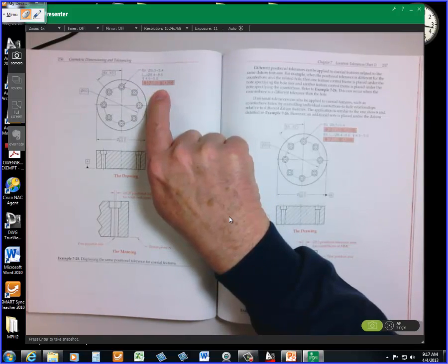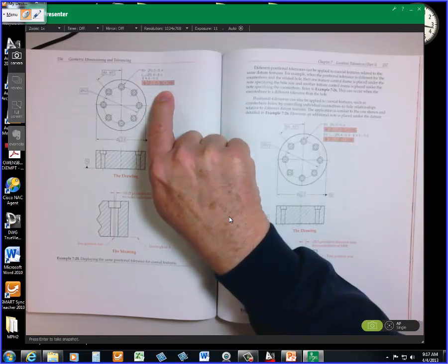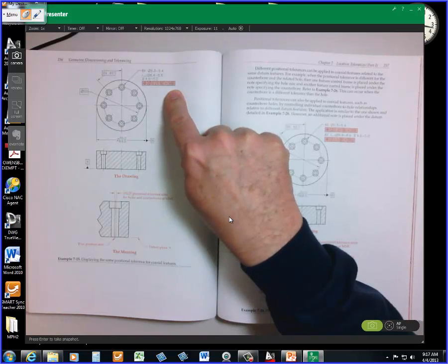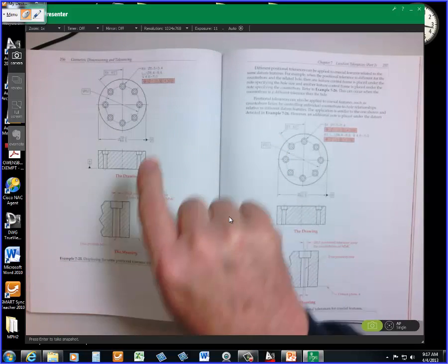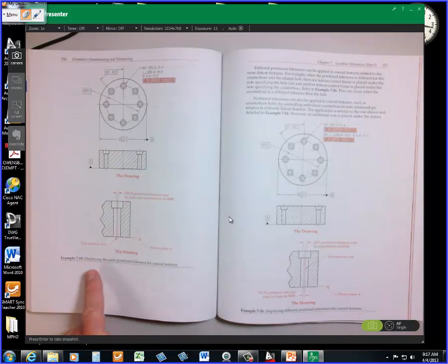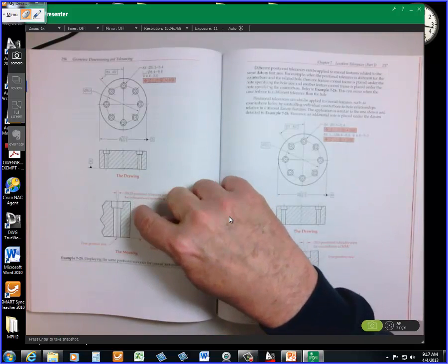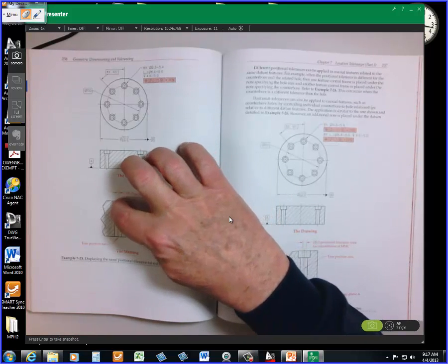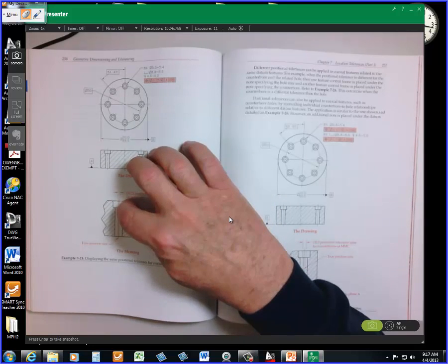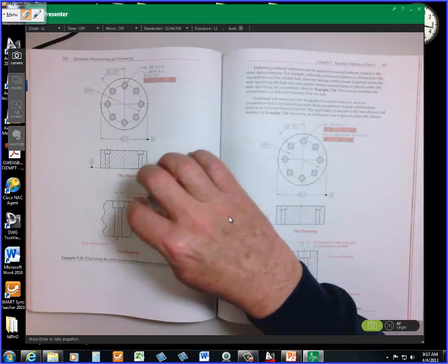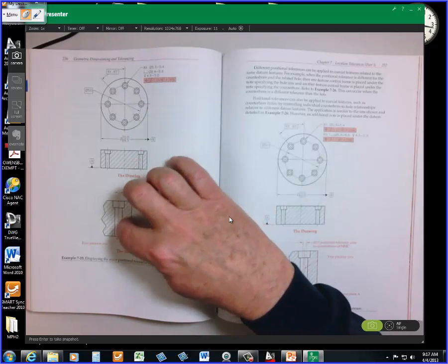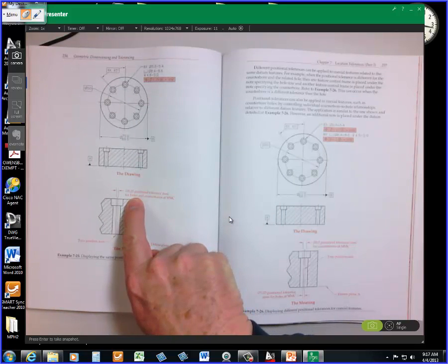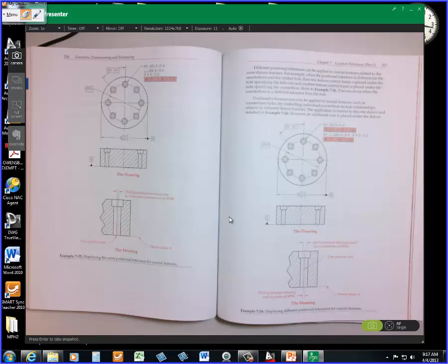Then we can actually create a position tolerance and make the datum B with a boundary. This essentially creates a situation where we are to consider the diameter of the bore and of the pilot hole sharing a 0.25 position tolerance zone in this case.